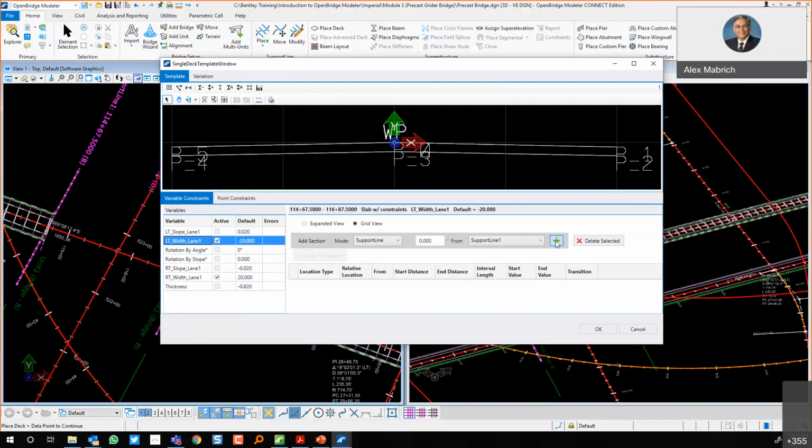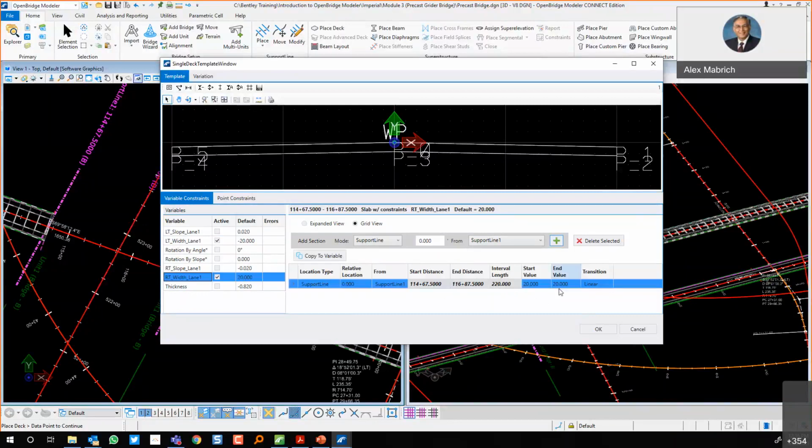no. Left click, and it says that according to the manual, one more time on page 23, this is going to be a 44 feet deck. So on the left is starting at minus 22 and finishing at minus 22. I think you got the idea that if you got a variation on deck width, for example, a tapering deck, one of the easy ways to do it is by a station, adding more stations and tweaking the numbers here. And on the right lane, you can do the same. Left click and say now it's 22 and 22.